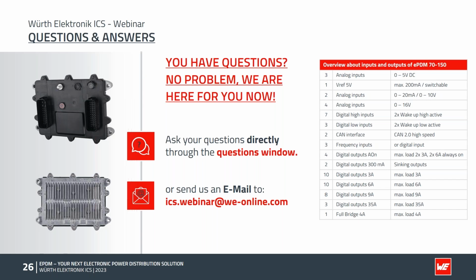Okay, we have a question regarding safety. Actually, this device will get the evaluation based on the 13849, so MTTFD, diagnostic coverage, and so on. The CPU which is used here is an S32K from NXP, which is ASIL-B capable.